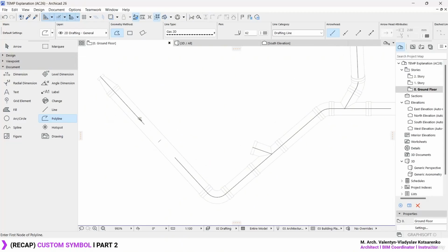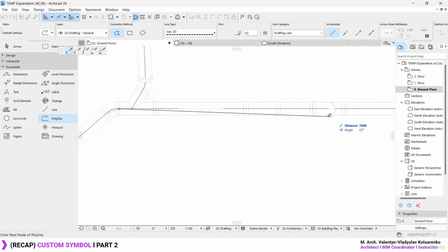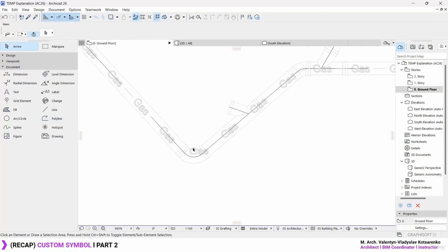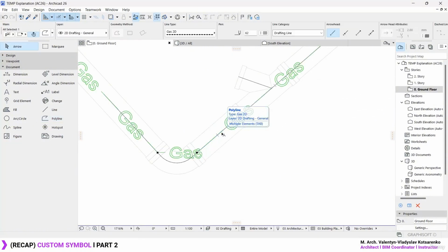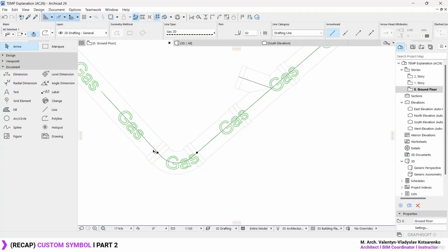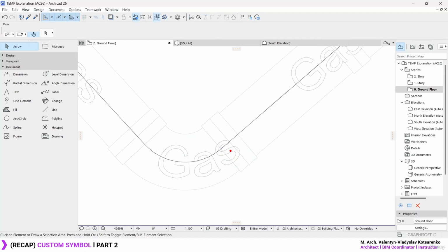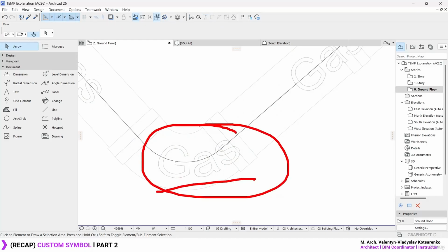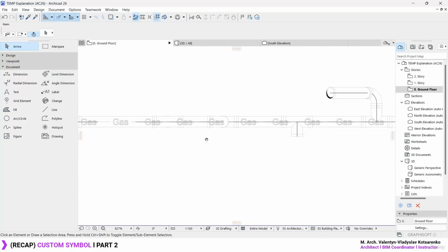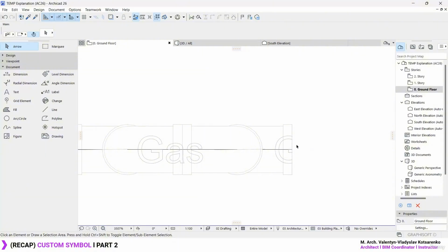No, it's not going to accept the Magic Wand tool. I was really optimistic there, but no, it's not going to work out. So let's go ahead and maybe draw everything manually, and then maybe adjust this just a little bit. Okay, so you can, for example, activate the polyline tool, select your polyline and adjust it so it matches the trace route over here. Just keep in mind that in these corners, it's going to look a little bit weird, but it's just this small detail. But everything else will be documented as best as possible.